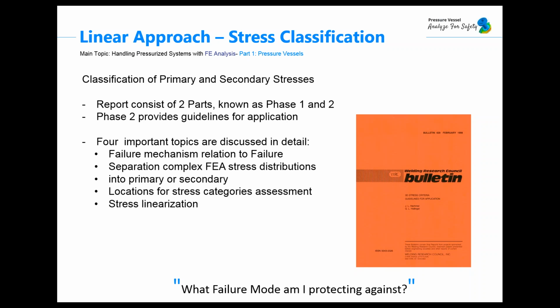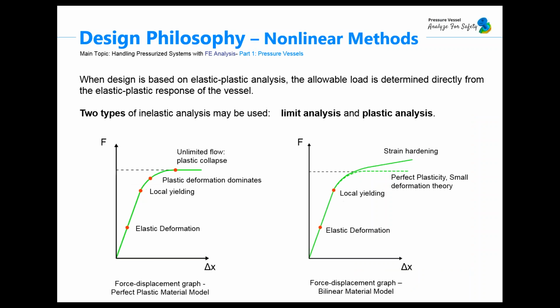And a lot of guides from this paper have been implemented inside the ASME code in regard to the stress linearization. So you can find a lot of important topics, like how to relate the failure mechanism to the failure, how to perform this separation process, how to classify these stresses into primary and secondary. Actually, it's not about how to classify, but it will provide you the guides on how to start. And of course, it's about the stress linearization.